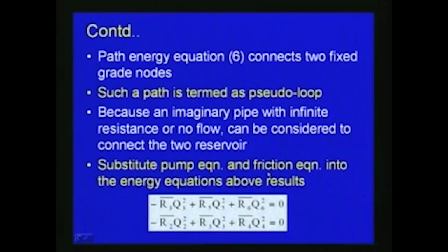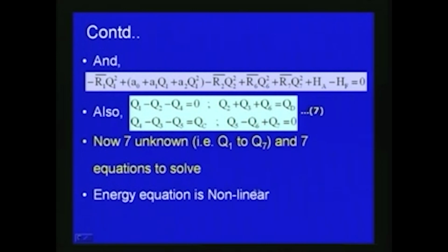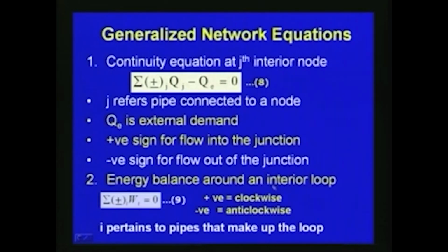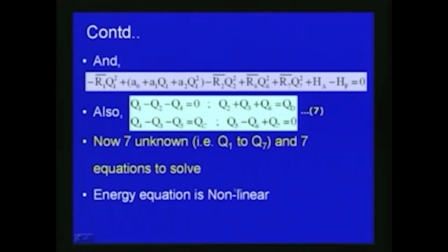But you can see that the energy equations are non-linear. So we have to either linearize these equations or go for an iterative solution. That is the generalization for this typical network which we have considered. We have seen how to write the various equations with respect to continuity, with respect to energy, and with respect to the pump equation.